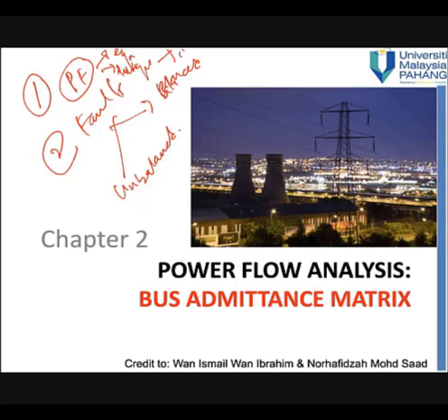Okay, number 1 technique is Gauss-Seidel. Number 2, Newton-Raphson. Number 3, fast decoupled. Okay, we try to learn about Gauss-Seidel today. Before that, we need to know that before we can construct the equation for the Gauss-Seidel technique, we need to know about the Bus Admittance Matrix.